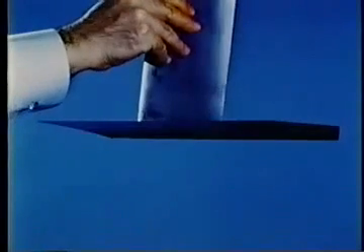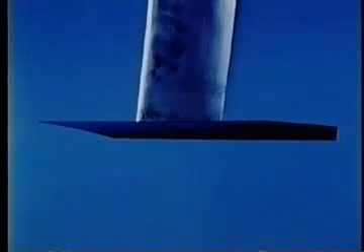When the leading edge is sharp, however, cavitation begins at this edge. This type of cavitation maintains itself as a continuous vapor-filled cavity, rather than a mass of small individual bubbles. Its size depends on the angle of attack, the ambient pressure, and the flow speed. The cavity grows when the angle of attack is increased.